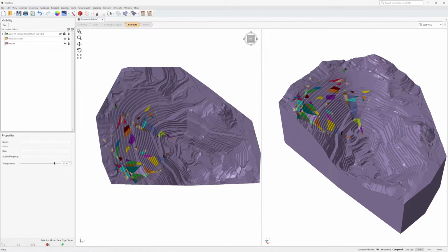The stability of key blocks control the global stability of the slope. As the key blocks fail and are detached from the slope, potential constraints in joint faces, in regards to removability and valid sliding direction, are removed and become free faces which no longer support the block or provide shear resistance to sliding. As such, the failure proceeds in a successive manner.